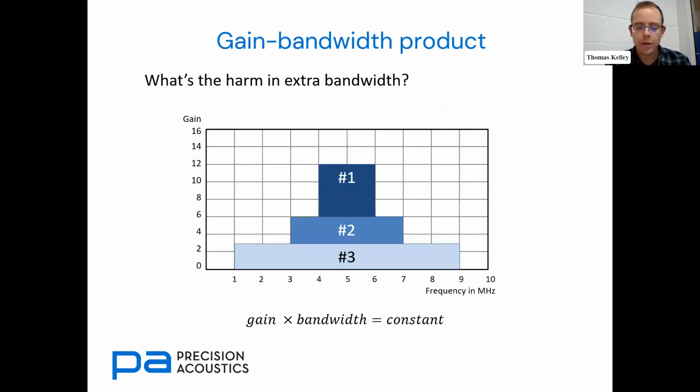So in a very brief summary, typically transducers with a high bandwidth will produce a lower output than transducers with low bandwidth. So high gain, low bandwidth, or high bandwidth, low gain. You can almost approximate it as gain times bandwidth is a bit of a constant. Obviously, there are things you can do to swing it around a bit, but as a general concept, that holds very well.